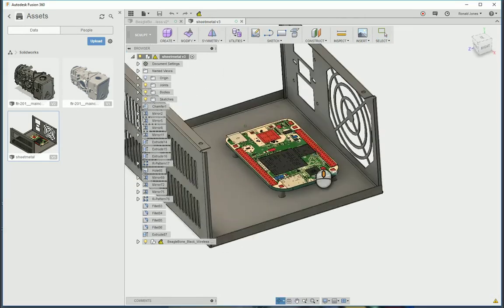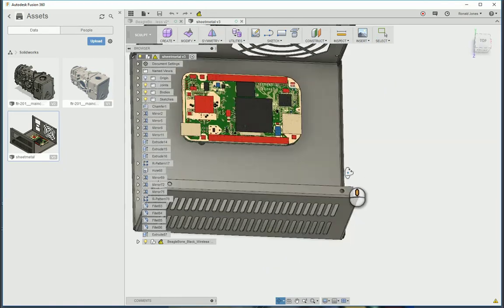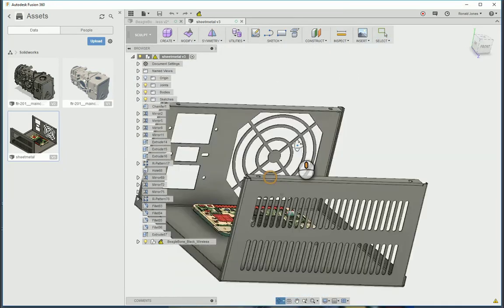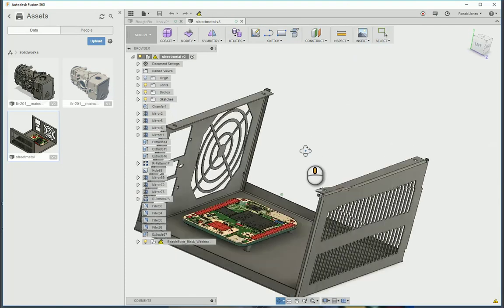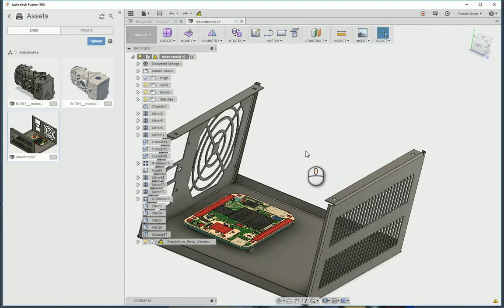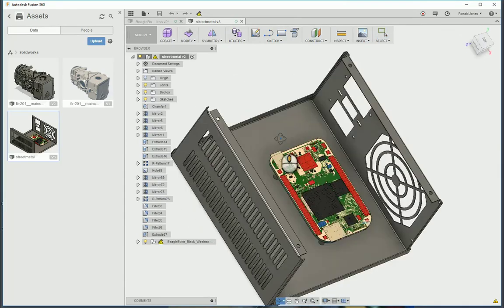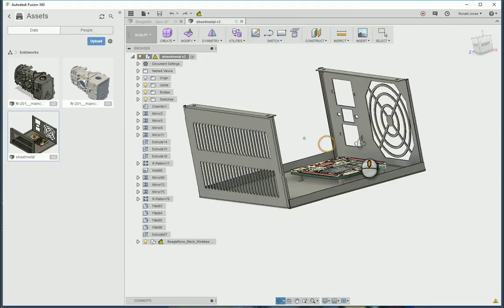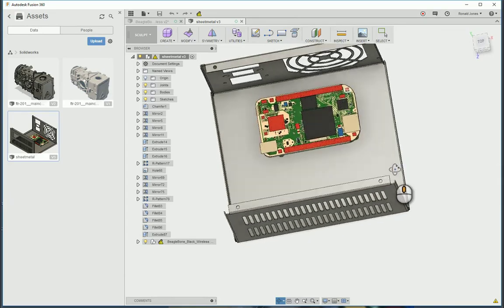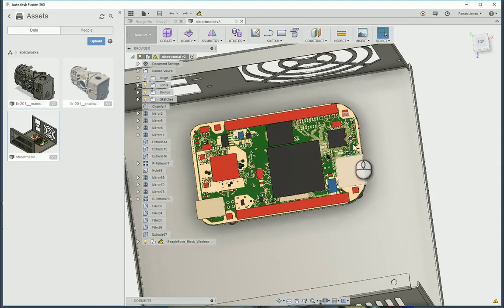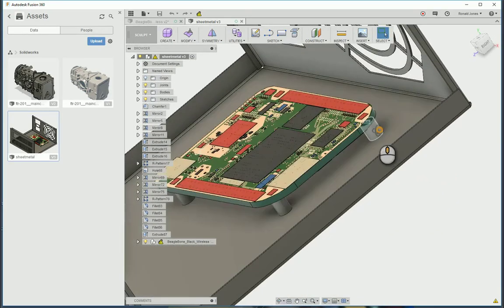You can see the next thing we're going to do here is we're going to actually place this into an assembly. So this will be placed into our power supply. And we're using the actual thing that we've designed. So of course with that link, if we need to make a change, that change is automatically propagated down inside of Eagle. Or if we make a change in Eagle, that change will then be propagated inside of Fusion 360.